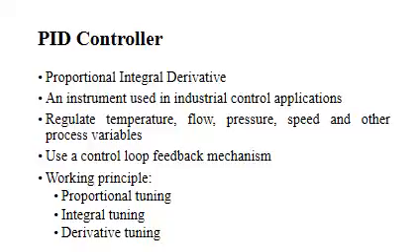Here are three steps. First, proportional tuning involves correcting a target proportional to the difference. Thus, the target value is never achieved because as the difference approaches zero, so too does the applied correction. Then, integral tuning. This attempts to remedy this by effectively calculating the error result from the previous action to increase the correction factor.